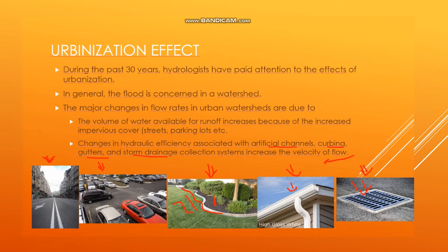It takes over the grass area and cuts the infiltration, so all these effects make ponding occur here or go through the channels, like here, the artificial channels, increasing the flow rate. Then this becomes a flooding problem, or like any other civil engineering problem due to water.